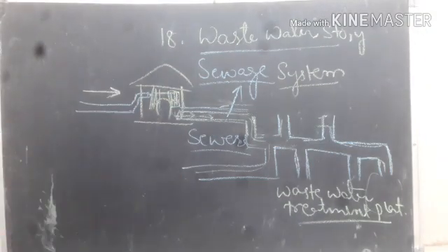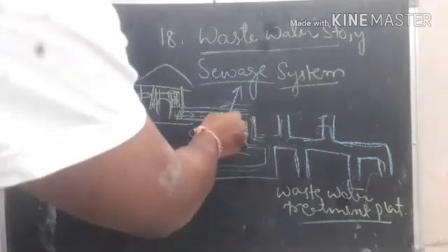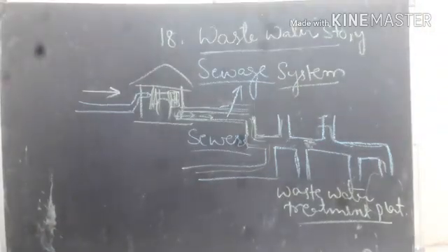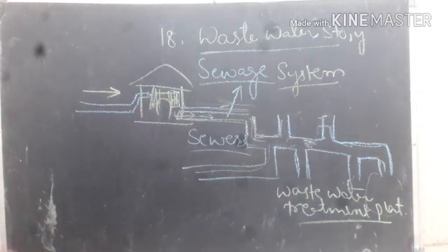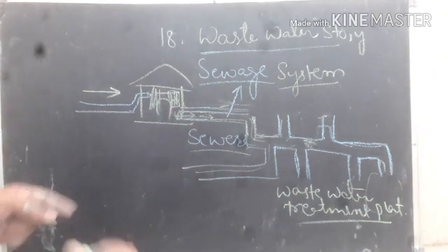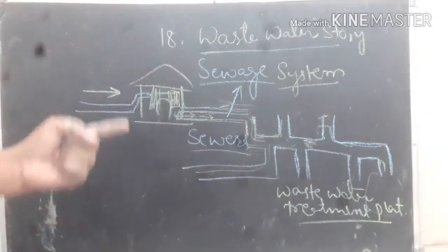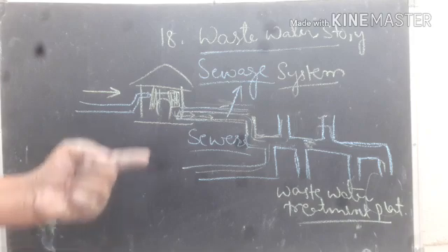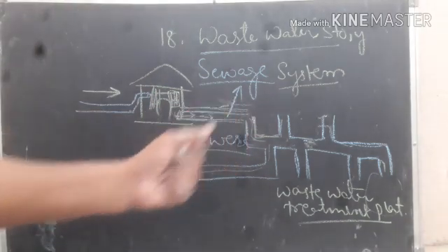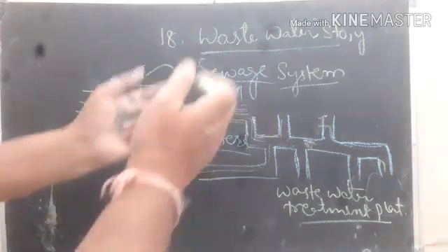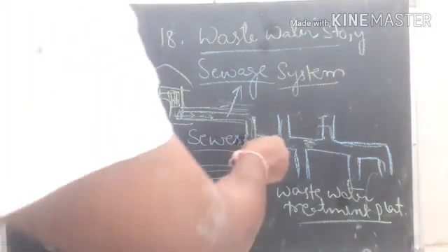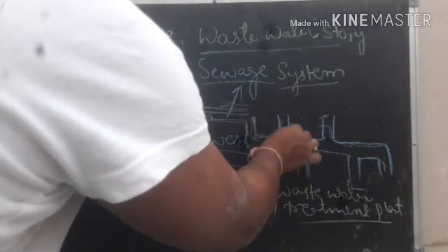Now, for example, if the sewage water is moving here and mechanical damage or something else happens in the pipe, how can we repair that? How is it possible to enter into the drainage pipeline? Actually, drainage pipelines are very huge in size compared to our pipelines. Then how can we get into the pipeline and remove the obstructed portion of the sewage? Simply, we use manholes.